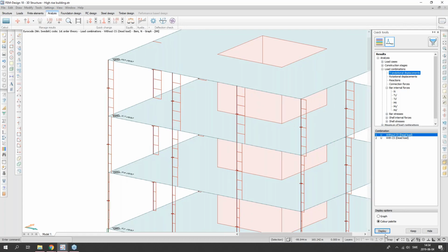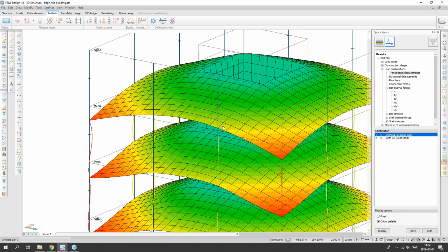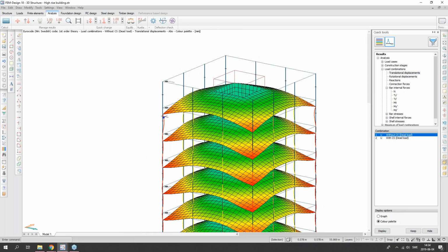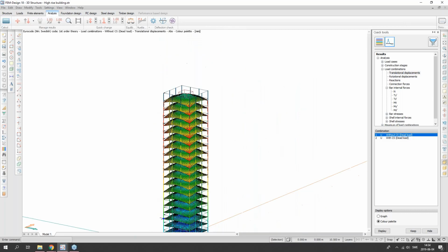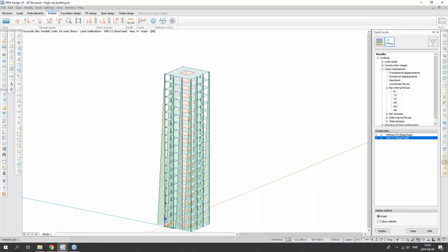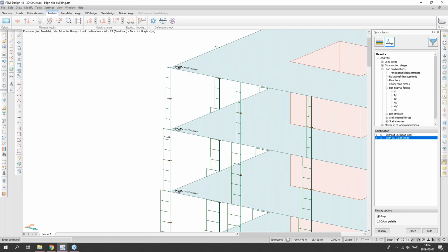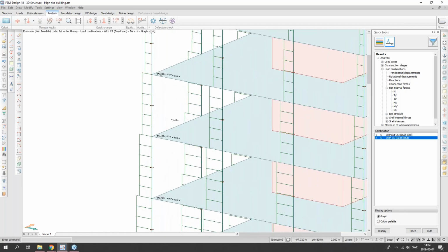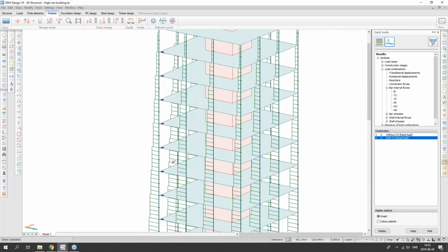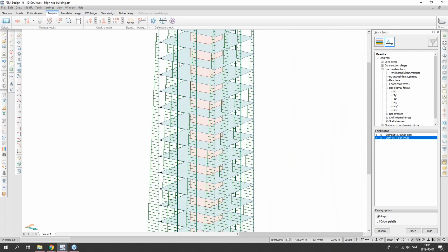So you can also see it if you look at the displacement. You can see that it's not resting on this column. This column is almost pulling the slab down instead. And this is because of the relationship of the stiffness between the column length and the slab cantilever. So instead, I want to check the results with regard to this construction stage. So in this situation, I have compression in all my columns, since I will reset the deformation between each step using the incremental tracking method. So this is usually more realistic behavior like this.